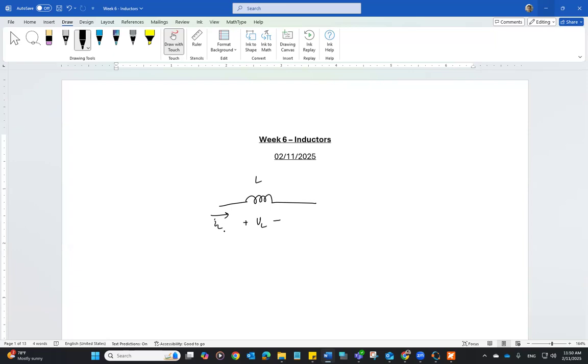As you keep running the circuit, the magnetic field stays but stops changing with respect to time. Then the induced voltage goes down to zero because the magnetic field is no longer changing. At that time, we say that the circuit is operating at the steady state condition.